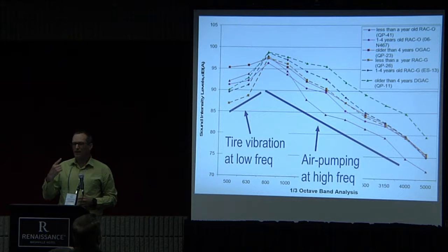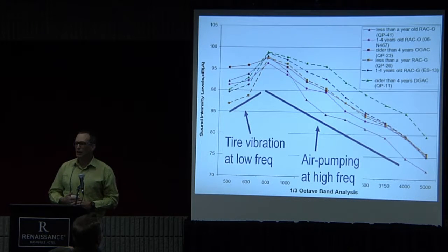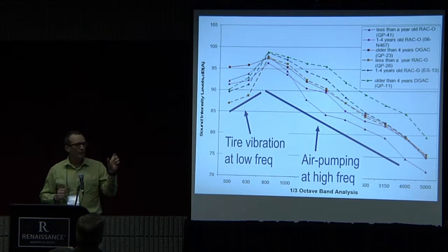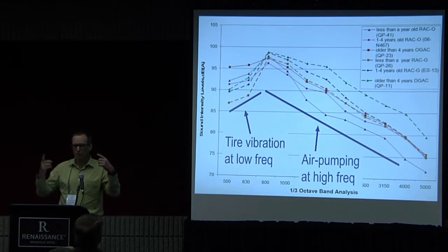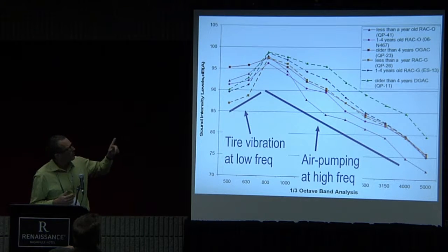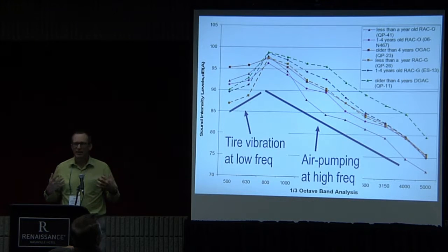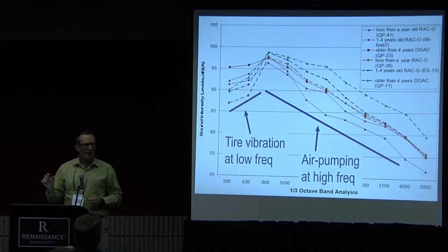Part of the reason that peaks at the 800 to 1200 hertz frequency range is because that's the range where we actually hear the best as humans. That's where human speech is primarily. So we partially peak there because of the weighting, but we also peak there because the size of the tire tread block snapping down and snapping up at 60 miles an hour is at 1,000 hertz.